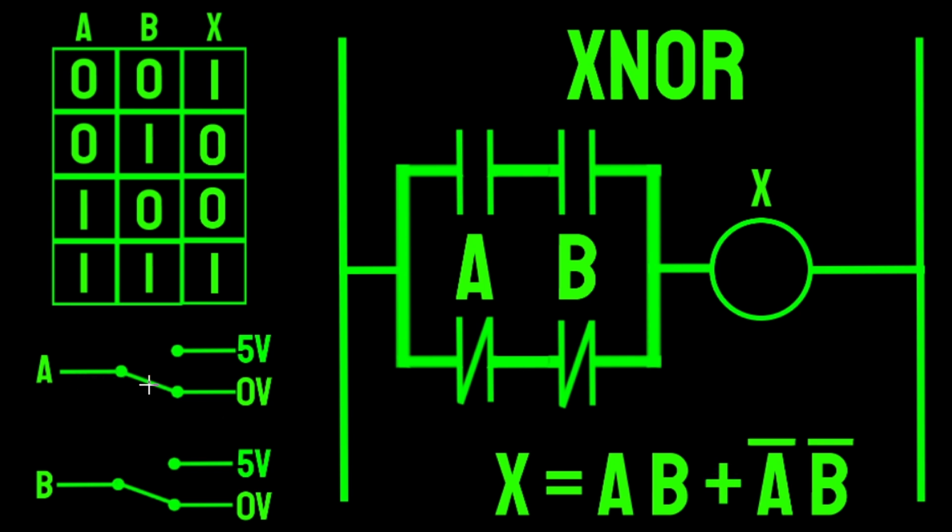In the de-energized state, where both of our inputs are low, our signal can come straight through the bottom branch because of our normally closed A and B contacts. If we energize our A input, both of our A contacts will switch states, and both of the branches will not allow a path for our signal to get through. If we switch both of our inputs so that A is low and B is high, all of our contacts will switch states, and we'll have the same condition where each path is blocked at some point and our signal will not be able to get through.